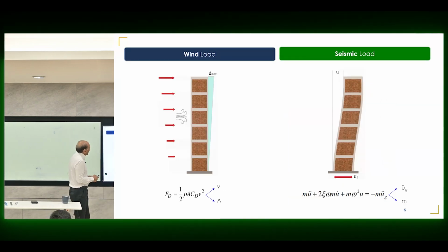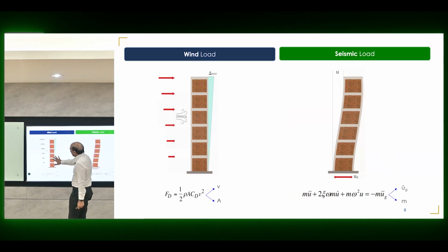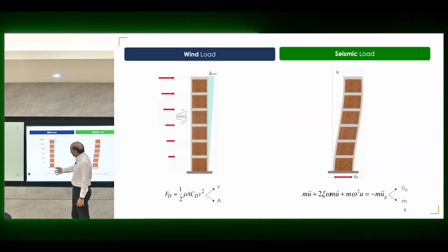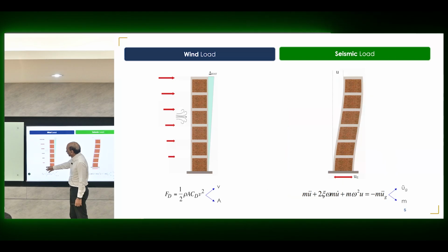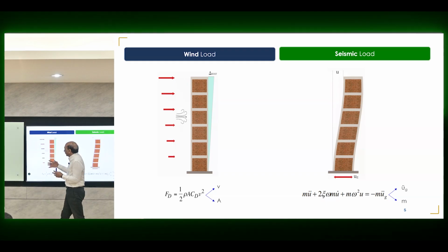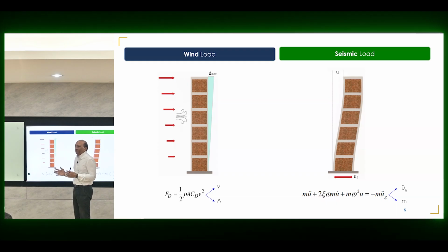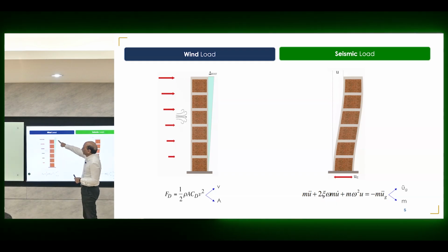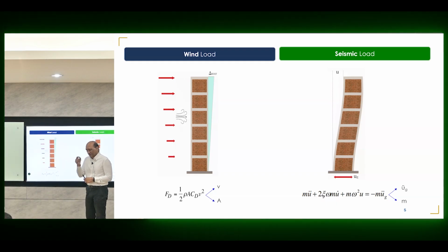And now look at this one. Basically, wind load, as I showed you earlier briefly, is going to be something like this. So it's going to be wind pressure, and there's going to be structure, and then the wind load will vary with height. It's a pressure multiplied by the exposed area, and it produces force. It will produce two forces, one along the structure, one across the structure. Both of them make the structure move about the foundation. And then we will have a roof displacement, which is going to be one of our criteria.